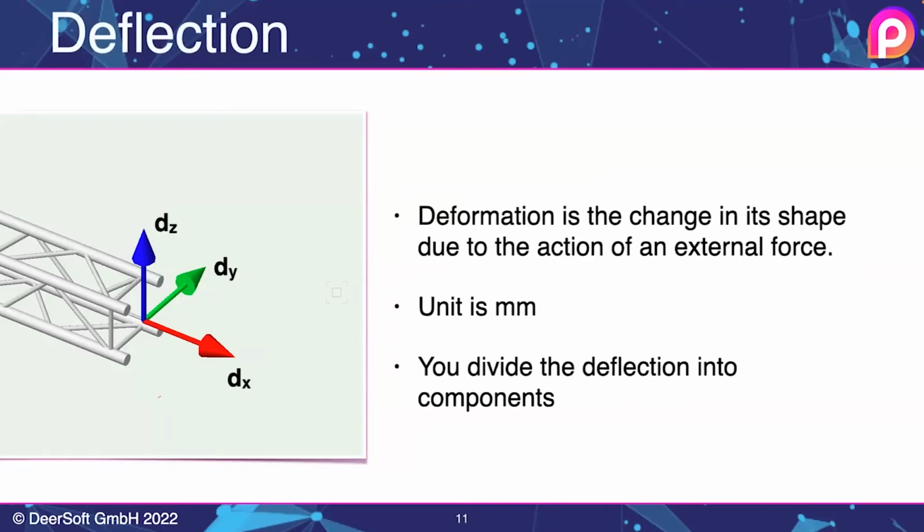Moments and forces are sometimes hard to read from the drawing when you don't have the background. Luckily, the deflection is really easy to understand. All bodies deform when you apply a load. Normally, human beings are really used to seeing objects deflect, and so can interpret this pretty easily to see if a structural calculation is valid or not. The deflection is also displayed in components, but you can also show the combined deflection that shows the addition.